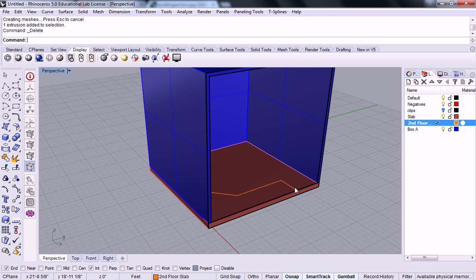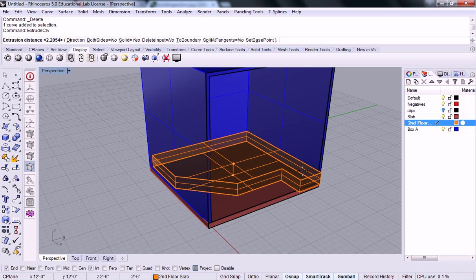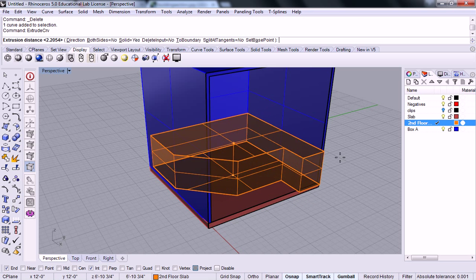So we're going to do a command called ExtrudeCurve. You click on the polyline, you type in ExtrudeCurve. CRV is short for curve. So you'll find that, for instance, when we did offset surface, it was offset SRF. And some of you had accidentally entered the command offset CRV for curve. So we're going to have ExtrudeCurve. There's also an extrude surface you see there, but ExtrudeCurve is what we want. And if you move your mouse back and forth, this is what you see.